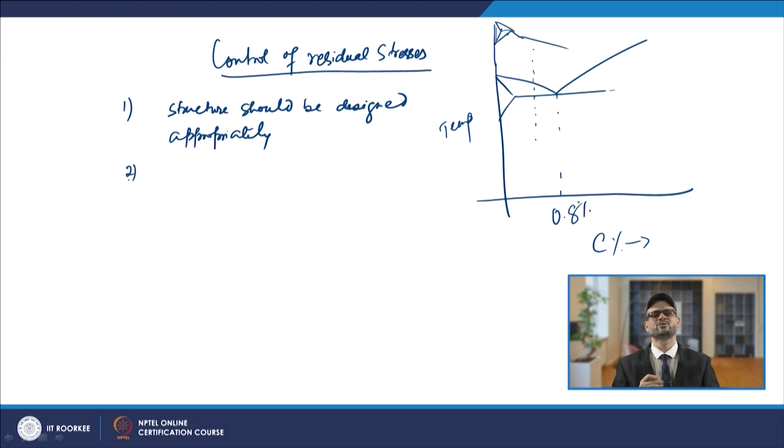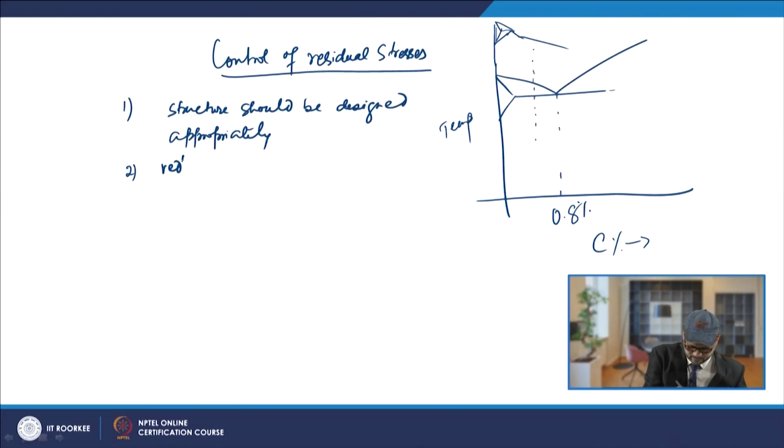So you should try to reduce the amount of weld metal. That will also lead to a lower value of the residual stresses.